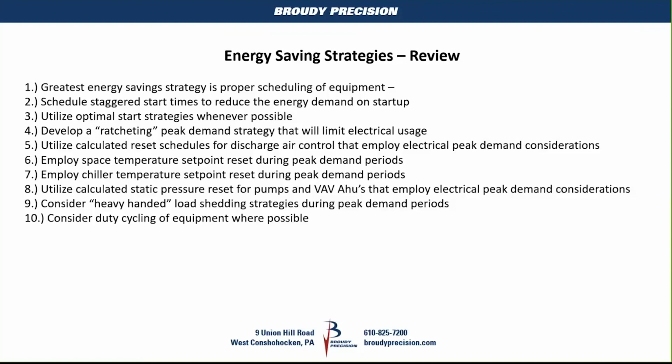I want to take my 74-degree cooling set point and bump that up to 77. By doing that, we close chilled water valves, or we shut off stages of DX. And by shutting down or closing chilled water valves, our chillers aren't under such great loads anymore, and they begin to cycle down. So those are some of the less heavy-handed methods that we're using.